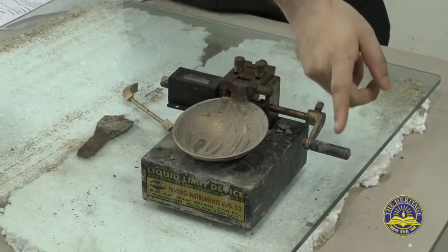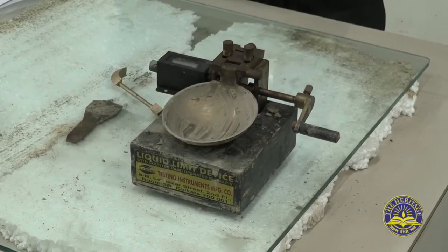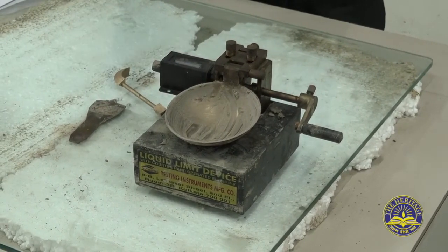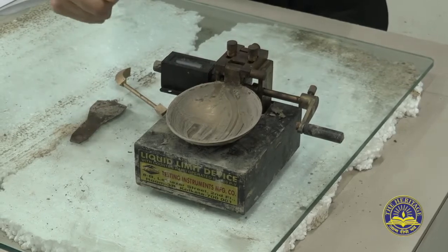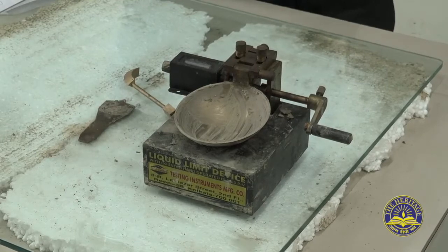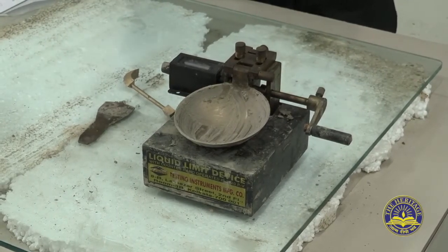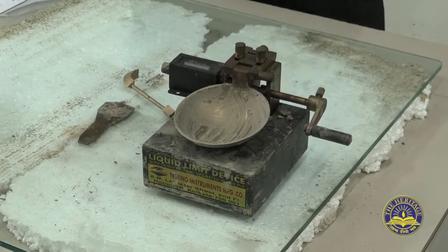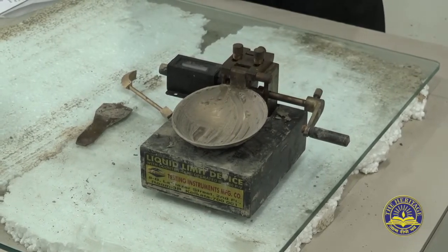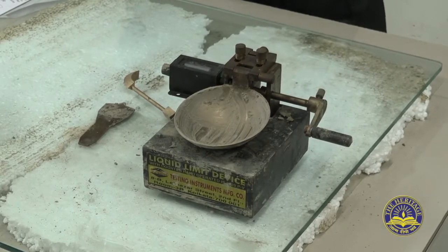And then you rotate with this handle and this cup will be like this, and after say 15 or 20 number of these blows, this groove will close, and when it is almost 12 mm closing, then you count the number of the blows and also determine the moisture content. So in this way you have to vary the moisture content and determine the number of blows, and that should be between 10 to 40, the number of blows.